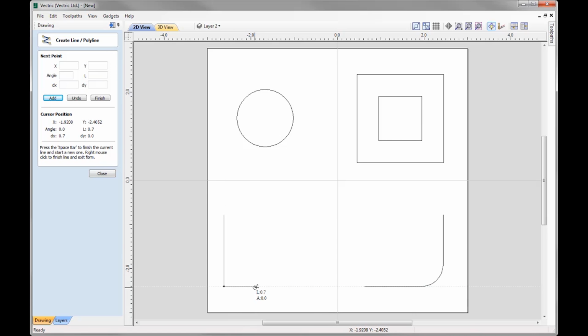and then I'm going to come across. You'll see now I've got a horizontal line. Again, really nice way for me to keep my cursor straight so I can create nice straight lines. I'm going to click that in place and go up, and so it's found the center object bounds for both shapes now. Okay, so it's found this one. It is actually this one that it's woken up, and I can tell that because of this dot here. And then I'm just going to go up, I'm going to align that to the top object bounds of the shape that I'm currently drawing. I'm going to click that in place.